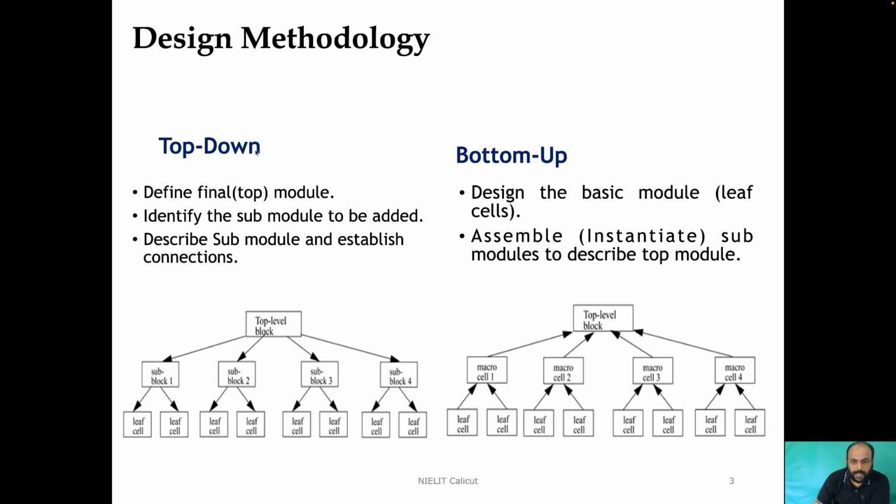Now when we talk about the design methodology supported by Verilog, we can go for top-down design methodology as well as bottom-up design methodology. Both are very intuitive. In top-down design methodology, we first go about describing the top-level block. Then the designer will identify what are the most optimum sub-blocks that need to be connected to achieve this top-level description. And the sub-blocks will be further divided into sub-blocks till we reach something called a leaf cell or the smallest building block.